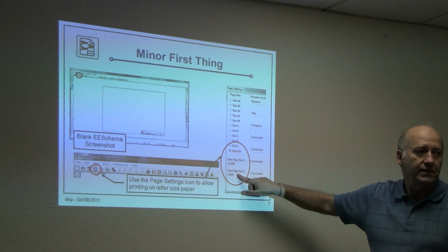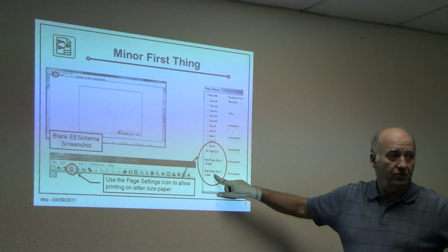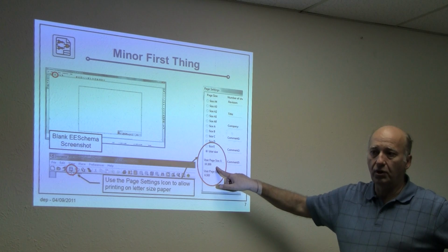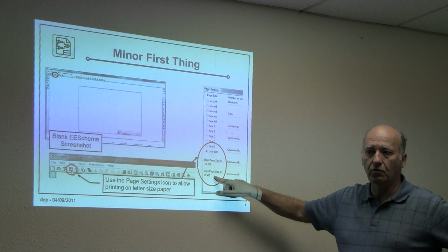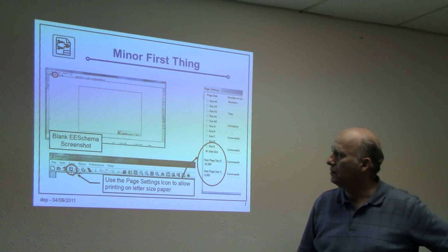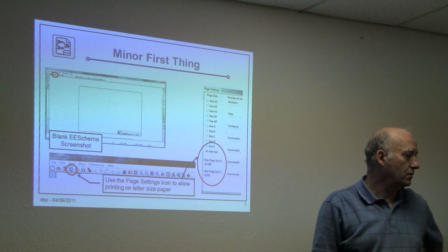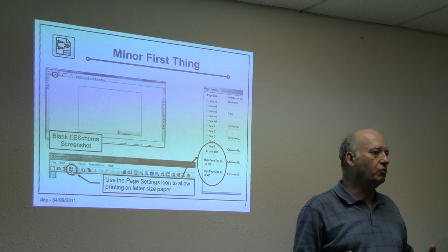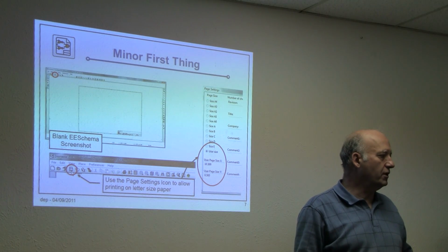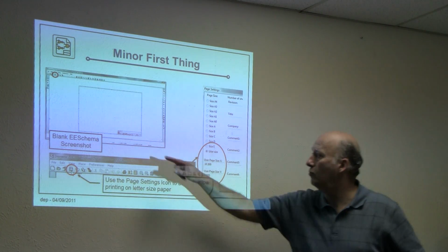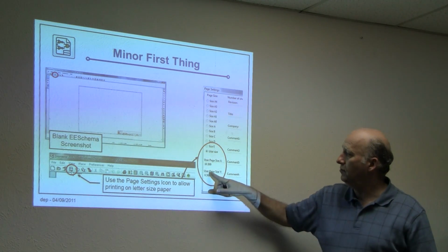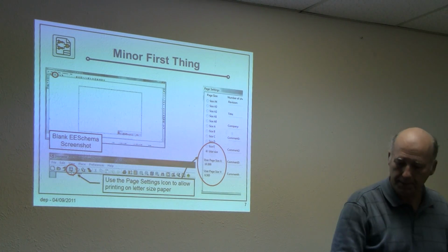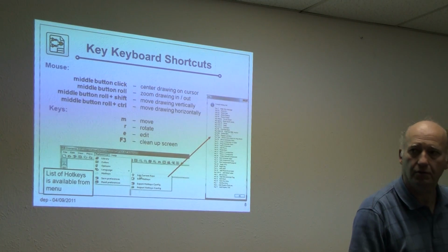Now, one of the things that I did find out on my HP printers, for some reason, I had to put 10.4 and 8.4 for it to work. On my Brother printers, no problem. So I don't know where that quirk is. It's a laser printer, that's the keep away. It won't print in the last quarter inch around the paper. So if you do the preview and it doesn't show the whole board, the whole border all the way around, knock these down a little bit until you do the preview and you see the whole board on it. Just a little tip you're going to run into.